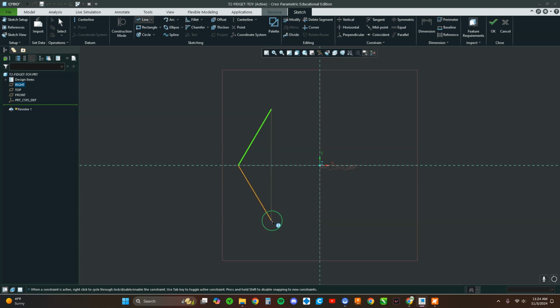Once you see that little dotted line, go ahead and click, and we'll go over to the left and see how we want a nice horizontal line. See how when I move over to the left, when it's horizontal, it snaps with a little inference line again. So we want that, and then we'll click, and we'll go up, and then I'm going to wait till I line up with this. Make sure I have a nice vertical line that lines up, click, and then we'll go over here, click. And all that is just going to save us some extra settings we'd have to make later.